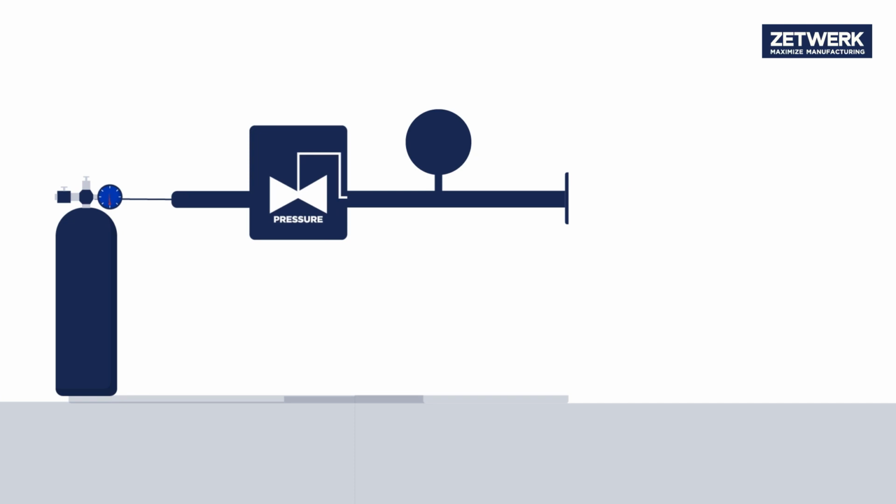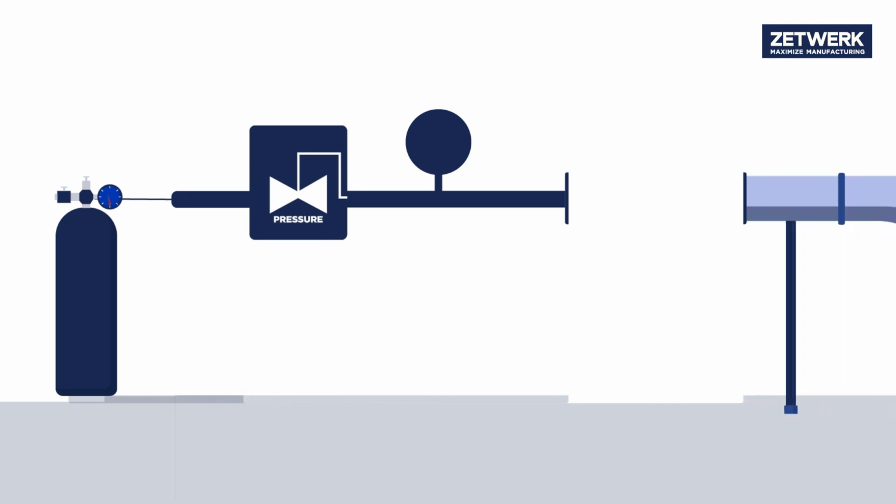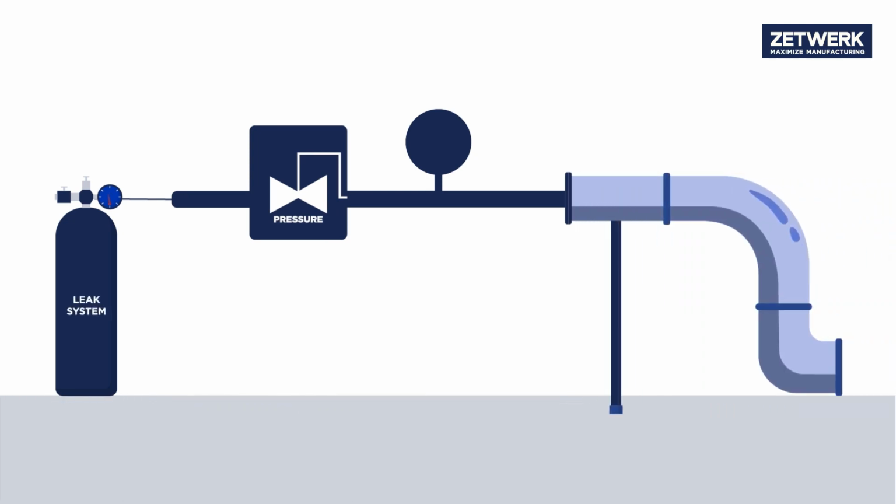In the pressure decay examination, for example, the product is attached to the leak examination system, which is filled with air. Once the pressure has been optimized, it is allowed to settle. Any decrease in air pressure over a given time will point towards a leak.